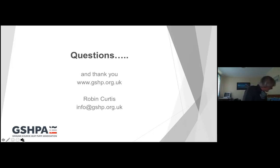Can I just add to that, Robin, by saying be very aware, or make the manufacturer of your expansion vessel, and particularly automatic dosing equipment, aware of the application and the temperatures involved in ground loops, because a standard offering can often get quite confused by what's going on and cause you more problems than it would help.